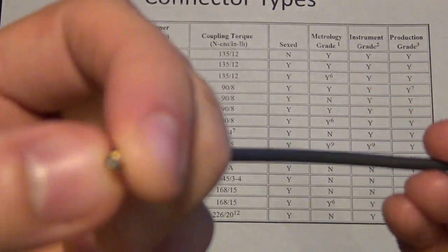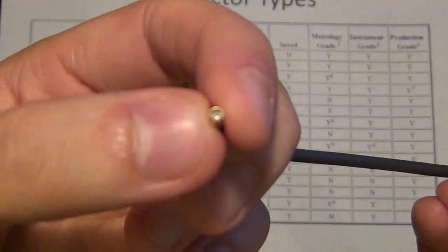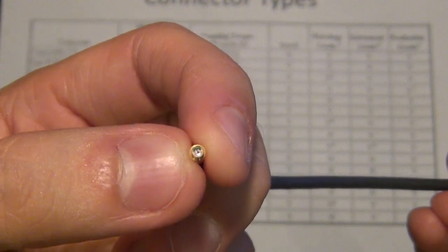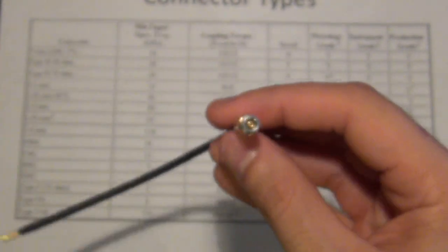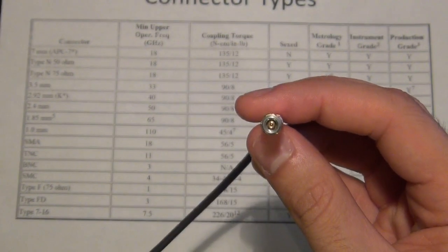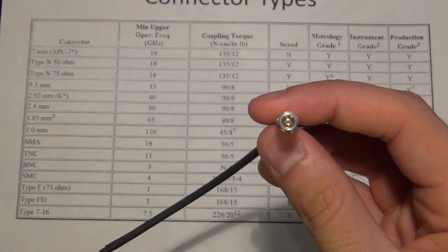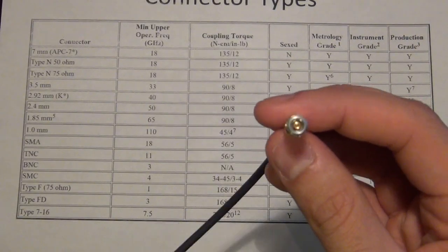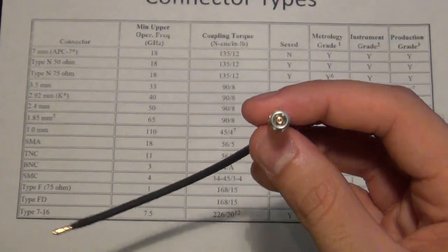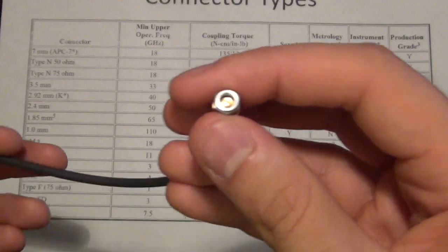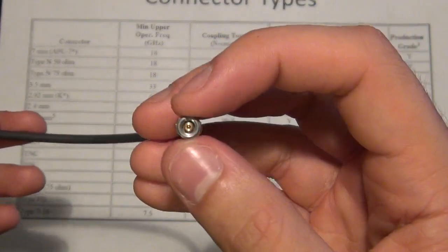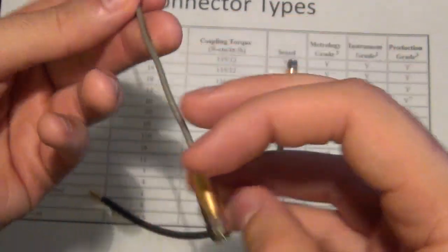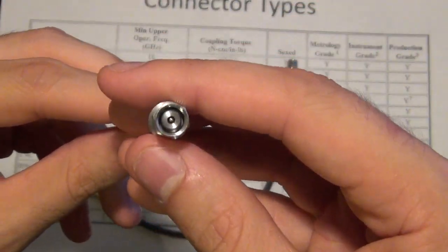And you can see on the other side, if it will focus, I don't know how easy it is to see, but you can see the center pin is tiny, very, very small. So Anritsu actually has a new connector for their network analyzer, which is even smaller, 0.9 millimeter, that will work all the way up to 140 gigahertz. And I think they're working on a 0.8 millimeter connector for even higher frequencies, but that's not very common, and only they're making it at the time, I believe. You can also get a 1 millimeter cable that converts directly to a V on the other side.